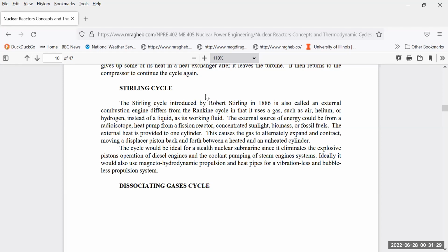In the space applications, you could use a radioactive isotope, or you can use some fission products, in fact, used fuel, to heat the working cylinder from the outside. So the Stirling cycle is suggested for specialized applications, and it has a fascinating possibility here in that it can attain the ideal cycle efficiency of the Carnot cycle efficiency.